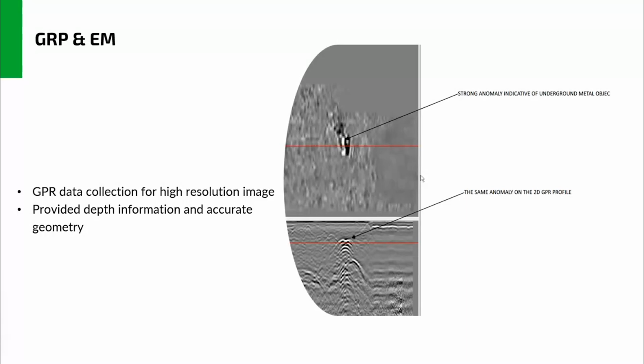If you look closer, by the way, you see that on this little snippet of the GPR analysis software, the top shows the map view and the lower part shows the cross-sectional view. It's just different than previously. And in the cross-sectional view, you see a really strong black and white, like two hyperbolas next to each other, visible.